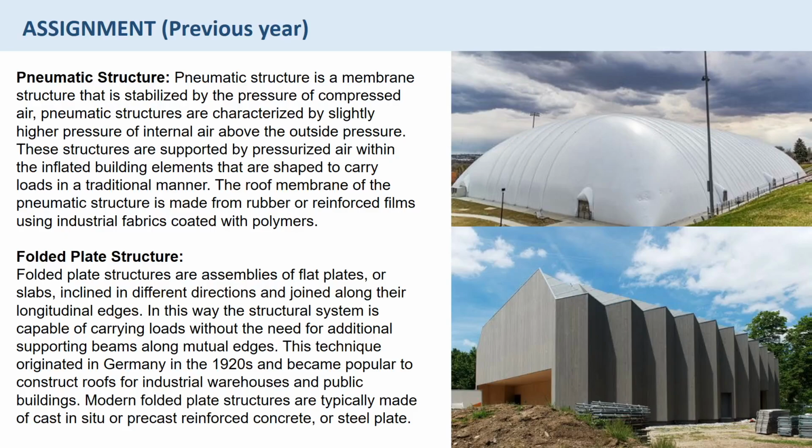A pneumatic structure is a membrane structure which is stabilized by the pressure of compressed air. Pneumatic structures are characterized by slightly higher pressure of internal air above the outside pressure. These structures are supported by pressurized air within the inflated building elements that are shaped to carry loads in a traditional manner. The roof membrane of the pneumatic structure is made from rubber or reinforced films using industrial fabrics coated with polymers like PTFE.